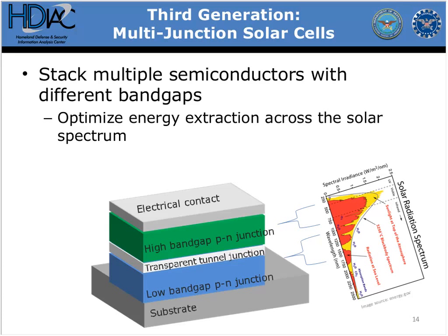But another potential application is in what's called concentrating solar, where you can have an expensive but small and highly efficient cell, and then have a bunch of optics over a large surface area that can collect a lot of sun and focus it onto this tiny cell. So even though it's expensive per cell, you can still potentially get some multiplicative effects, capturing a lot of area using very cheap optics. So multi-junction cells, complex, but very powerful potential.